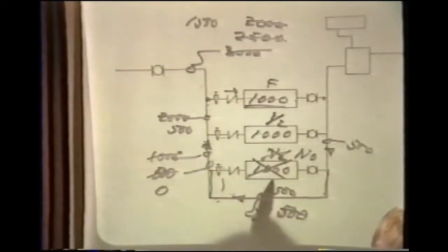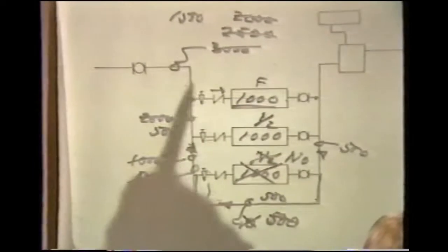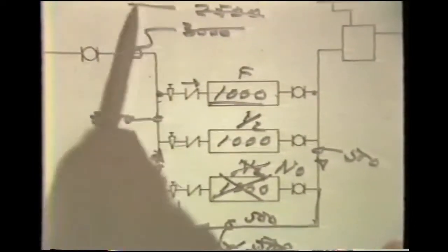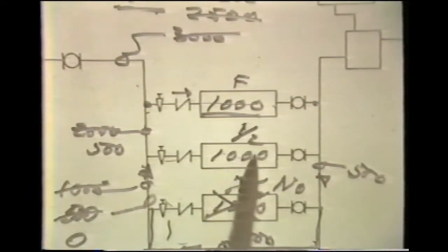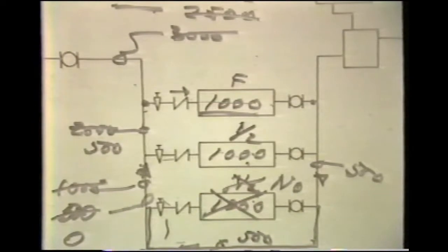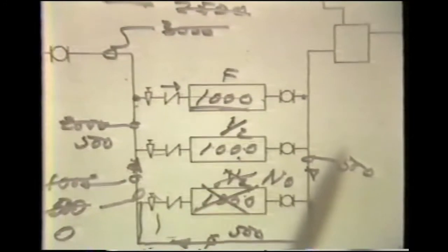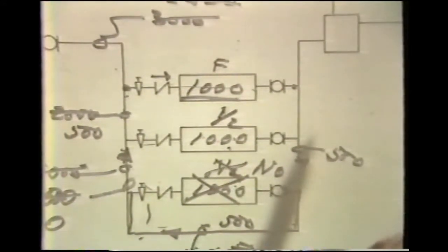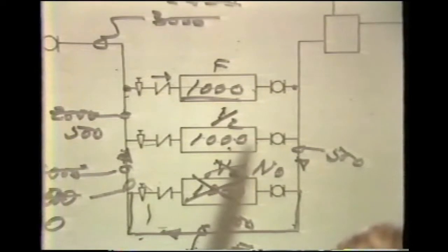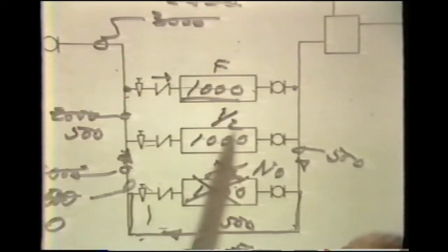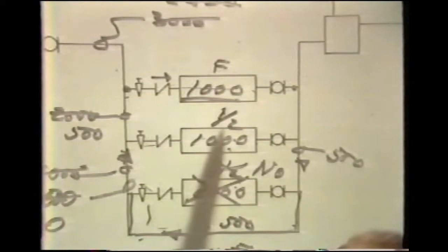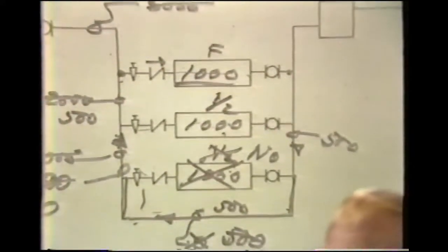And the loading of the chiller then goes on and off depending on the flow rate change in the distribution main as compared with the pumped flow in the chillers. This, of course, eliminates the need for the control devices in the common piping, the flow measurement devices in the common piping, which actuate, in the classic example, the start and stop of the chillers. Now, proceeding from this then